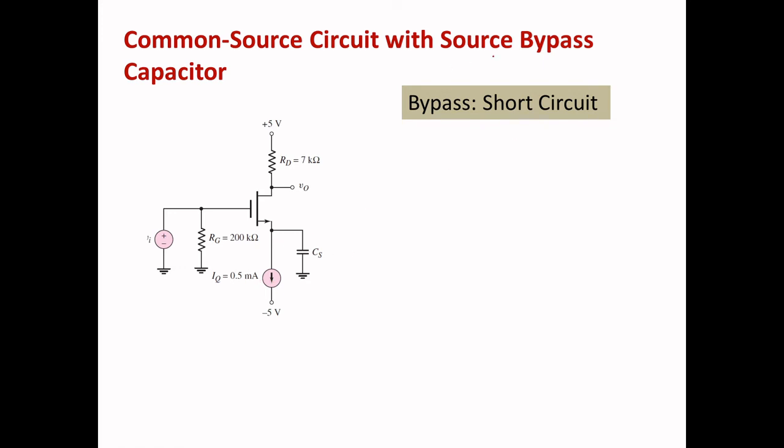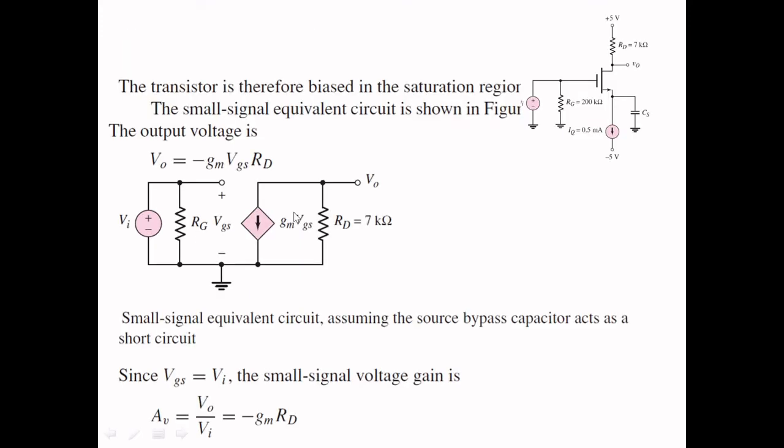Just see, you have a bypass capacitor. You have only the bypass capacitor. So when you connect it, how is that model going to change? Then what is the equivalent circuit that we are going to discuss now. So for this circuit, this is your equivalent model. Same procedure: gate, drain, source. So you can put your terminals, gate, drain, source.